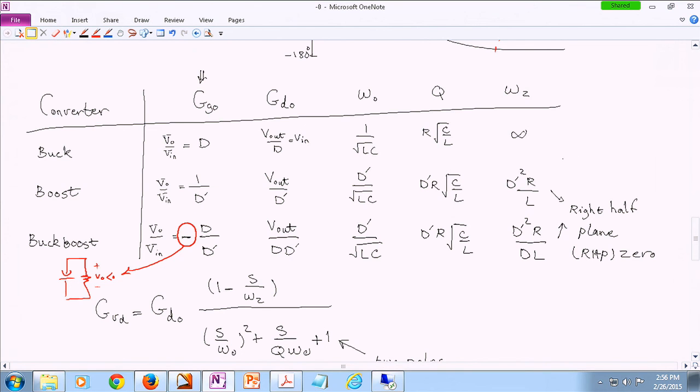Okay. To summarize, we would encounter this problem only at very high frequencies. Normally you would encounter these problems at kilohertz only if omega z is dominating. Okay, let's talk about the word dominance. If it is a dominating zero, or a dominating non-minimum phase zero, it means that in terms of value, it is smaller than the other zeros and poles in the system.